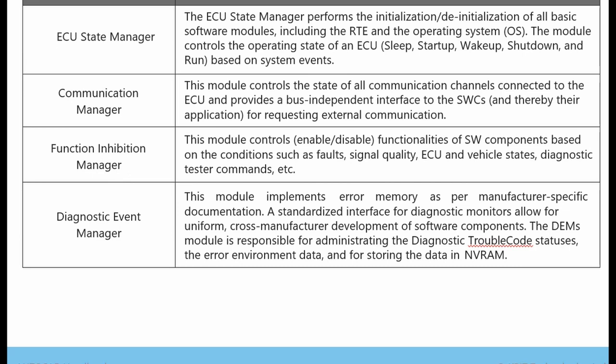I will explain these concepts in my upcoming videos. So, vehicle states, diagnostic tester commands, etc. Then you have the diagnostic event manager. This module implements error memory as per manufacturer specific documentation. A standardized interface for diagnostic monitors allows for uniform cross manufacturer development of software components.